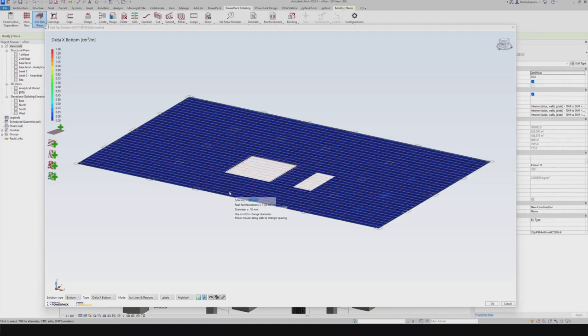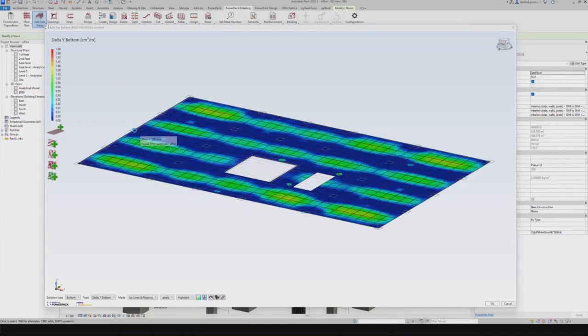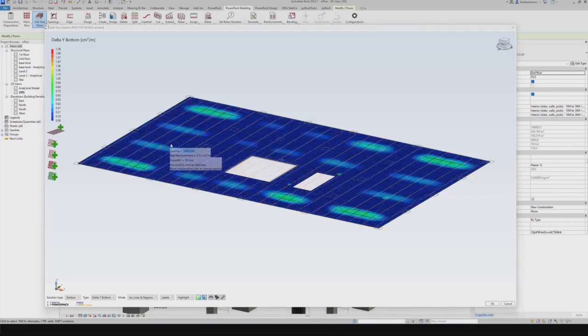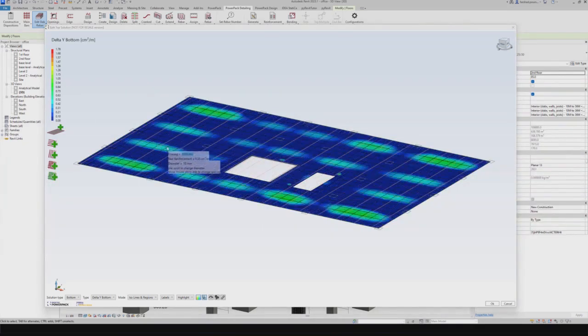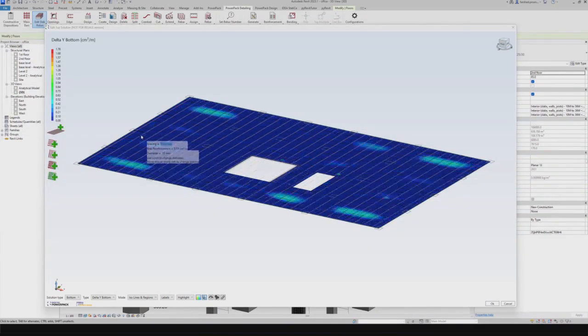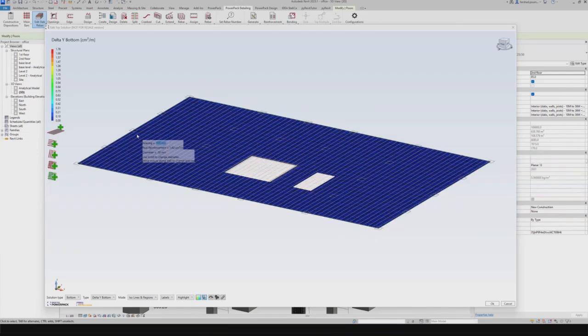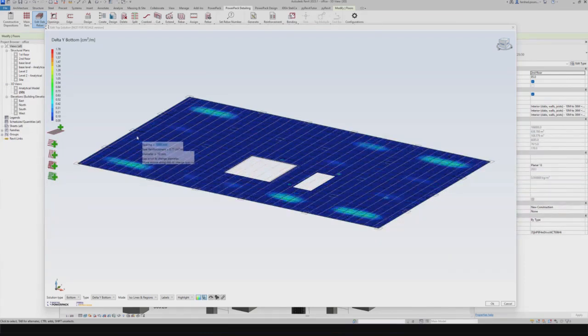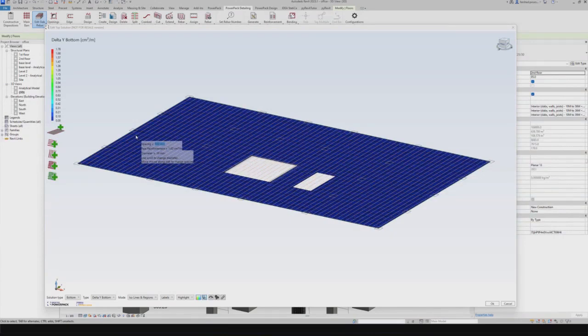And now I've added that direction of rebars, and now we're going to be working in this direction. Basically, same scenario here. I can start with, let's say, 300 millimeters, and again, based on my finite element rebars, I can put my rebars in a very economical way so that I'm not using a high value of steel. So that's it, I'm covering it now. Click OK. And now this rebar will be applied to my Revit. So there you go. And if I click OK,